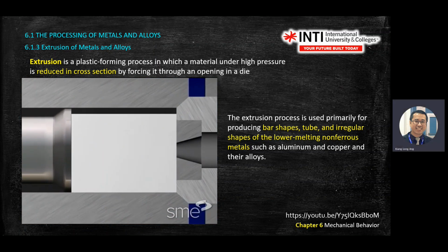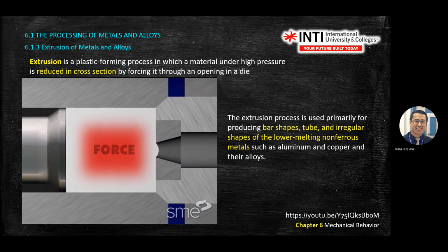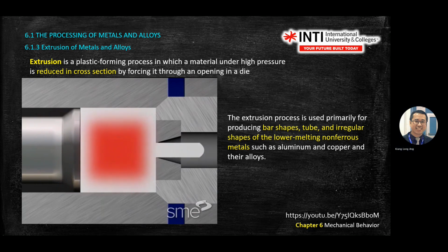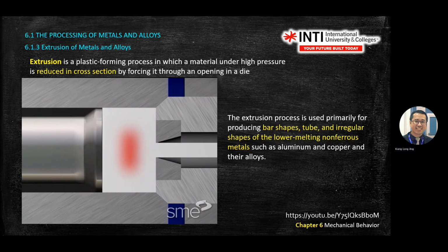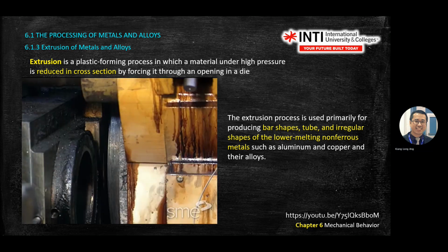See on the diagram, you try to force the metals into the opening of the mold. If you're a designer of the mold, be careful of sharp corners, and you need a lot of lubrication in the mold, and you'll create heat also.